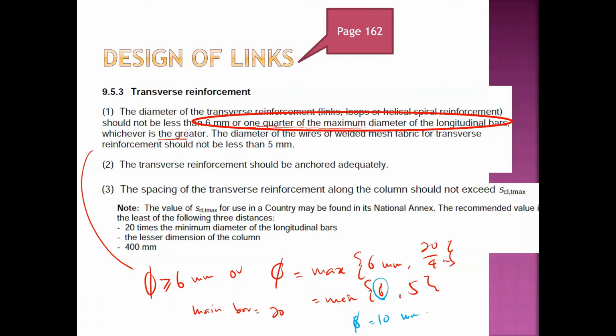And then the spacing. The maximum spacing, you must select the value that is the least. The least means the minimum. You select the minimum between these three: 20 times the minimum diameter of the longitudinal bars.